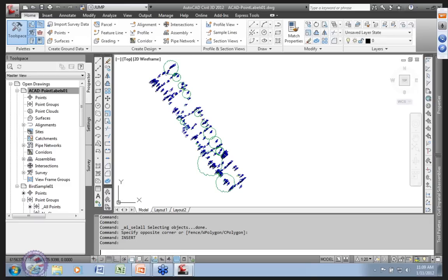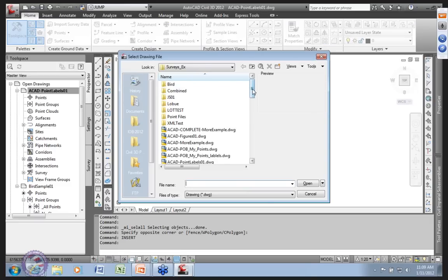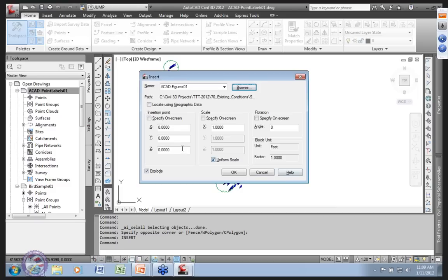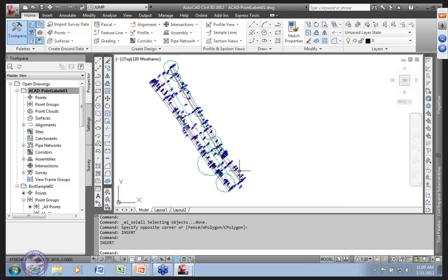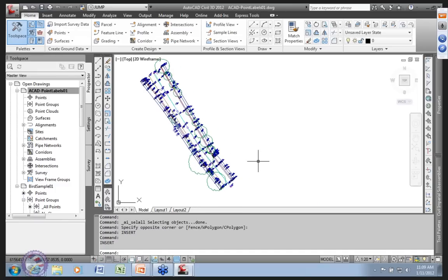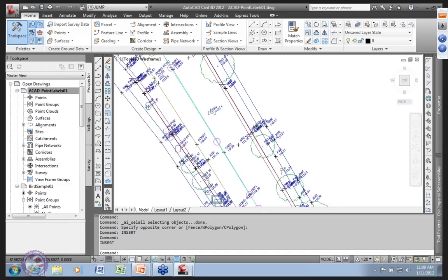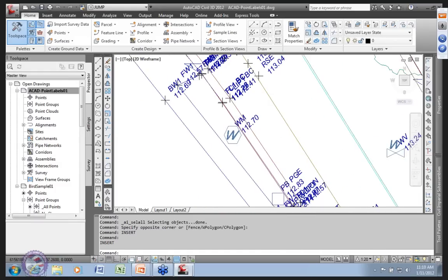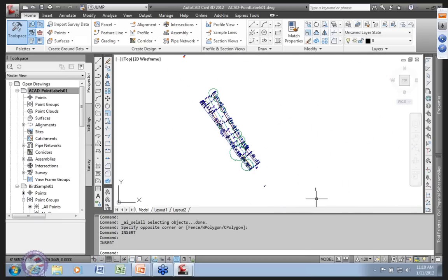And now I got my symbols, and now I simply pick one of my figures, and once again, please locate that way so it's all stitched back together, right? And now I have hit save, and I have an AutoCAD drawing with all of my figures, pure AutoCAD stuff, reasonable annotation, all at the right scale. And hey, fixing things I would fix before I went out to AutoCAD, but if you want to offload the rotation work and those sorts of things to someone else in the organization who's Civil 3D skilled, you can do that.